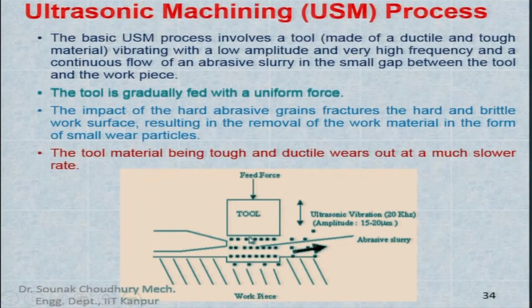Therefore, the frequency and the amplitude given by the tool are imparted on each of these particles, and with that frequency and that amplitude the particles impinge the surface, which is a hard and brittle material. So it will have a brittle fracture, and that fractured piece of material will be removed from the surface.